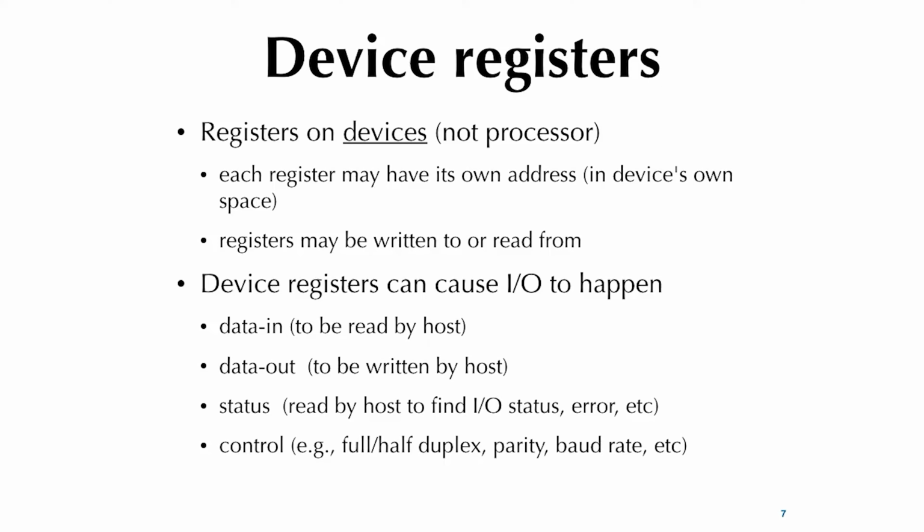So these registers, well, on 8051 you can read and write them directly using a move instruction. But if it's an external device, then you have to send a little packet over the bus that embeds the read or write. Well, you have to name the register, because a register would have a name, and it's most likely some numeric name or the address. So even 8051 registers R0 to R7, you can think of them as address 0, 1, 2, 3, 4, 5, 6, 7. Those devices have their own addresses in the device space, and you read and write them. So you pack up these commands.